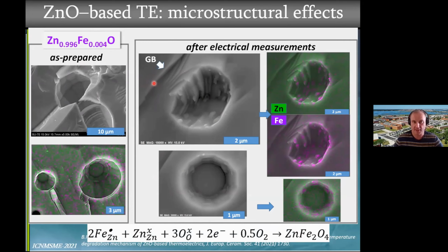So what is happening is that relatively fast cooling of ceramics after sintering actually avoids any defect segregation. You prepare your material in the furnace, you sinter, you cool down, and the impurities don't have time yet to leave, to go out. And also you have some kind of freeze in the high temperature defect structure.